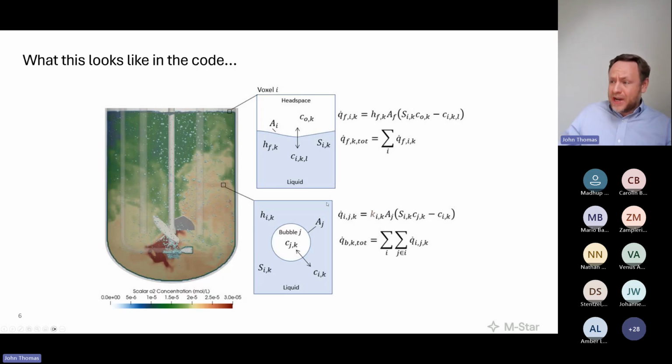And again, oftentimes people measure KLA, well, I'll use that term. We use it so loosely. I measured KLA. No, what you measured was the time evolution of the dissolved oxygen concentration, and you ascribed it to bubbles and then projected it onto a KLA model, which is fine, but your probe may, again, as I've been speaking to, have been adulterated by this additional oxygen transport coming from the headspace, and you're shoving that all in the bubbles when the bubbles may be getting credit for work they didn't do.